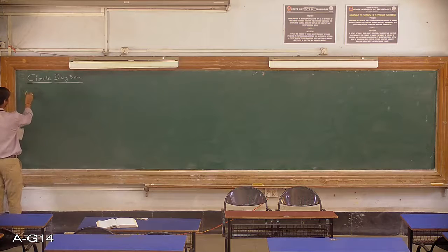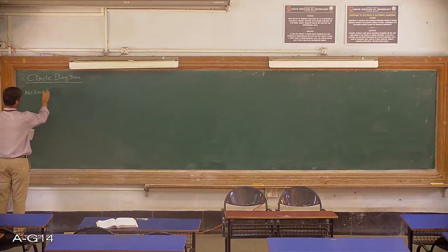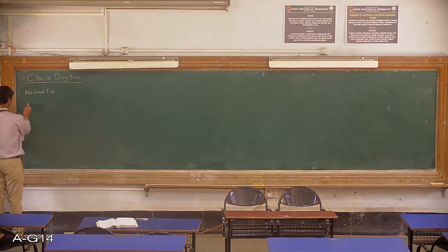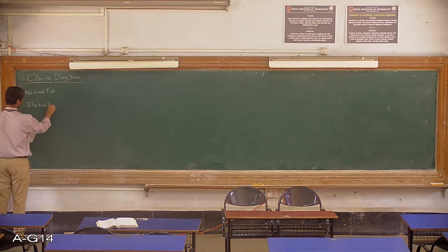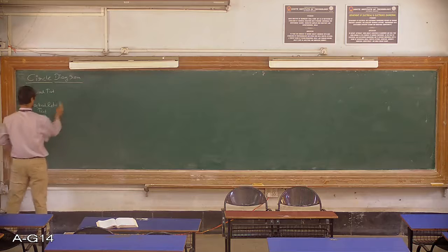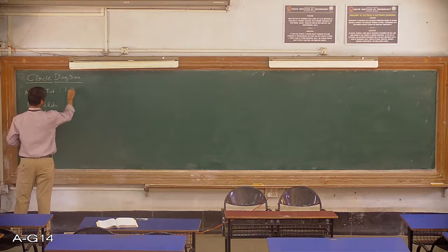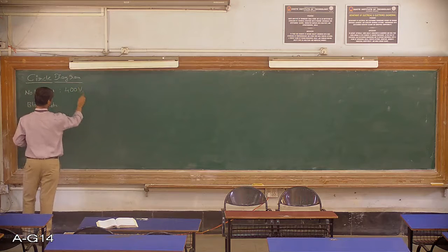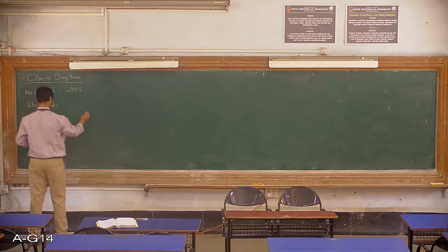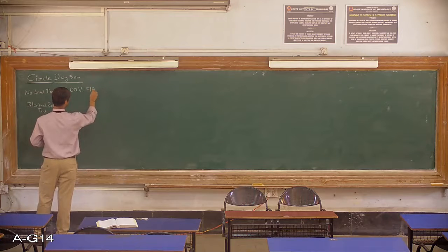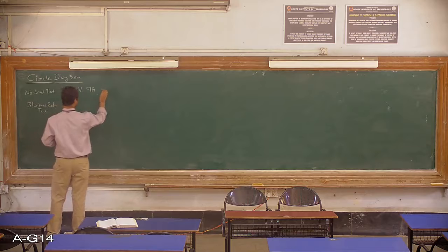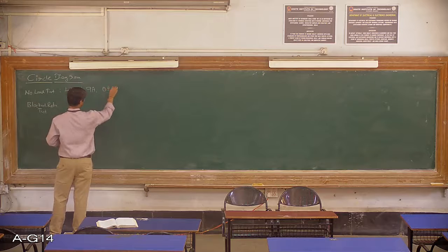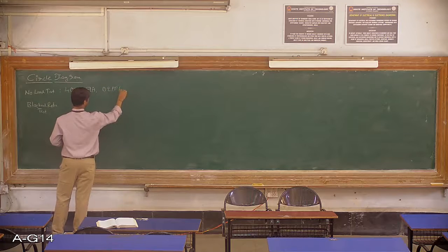I'll write them down here. No load test results and blocked rotor test results. For this, it is 400 volts, 9 ampere, 0.2 power factor lagging.